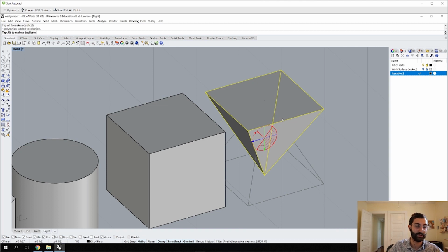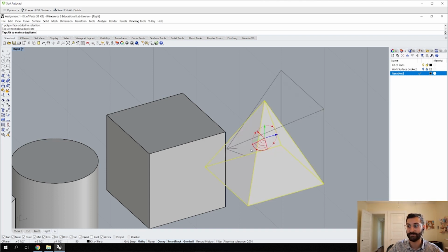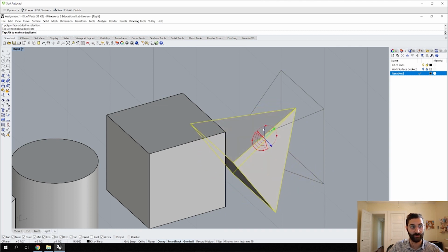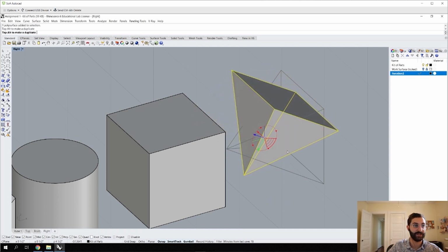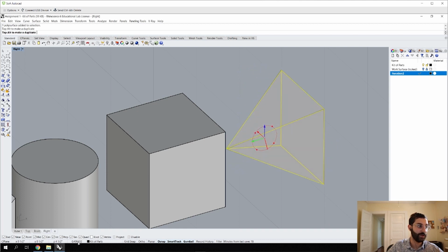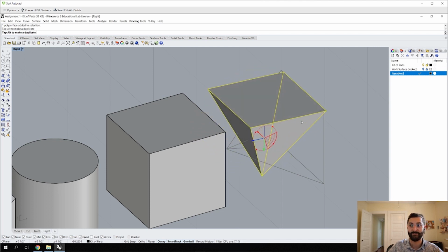That's really helpful because the reason why it's doing that is because ortho is selected, but we can easily override that by holding down shift, the shift key on our keyboards. And then now, as you see, when I do it, it'll rotate like to whatever number we want. And then also on the bottom left-hand corner, I'll move my mouse over to here. You can see this number changing. That's going to be how much we're going to be rotating, and you can do it by precise numbers, or you can just follow that and be in precision.